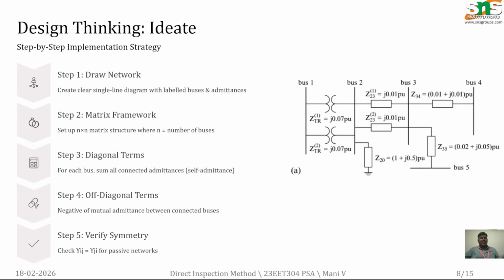And next, the diagonal terms. For each bus, we have to add all the diagonal elements and put them in the diagonal value. That is like y11, y22, y33, y44.